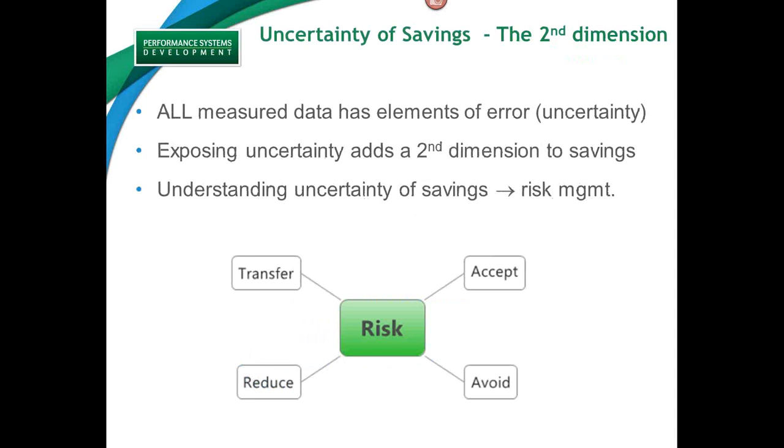Another piece on this, which has to do with measurement and verification, is talking about the uncertainty of savings. I call it the second dimension. If you look at how many of us, including myself, a few years ago, it was not uncommon to hear me state some sort of savings just as a net number. We believe this investment will save this many kilowatt hours over this period of time. Purchasing a new chiller would save you 1.5 million kWh and reduce your demand by 600 kW over a typical cooling season. That again is a prediction coming out of an audit.